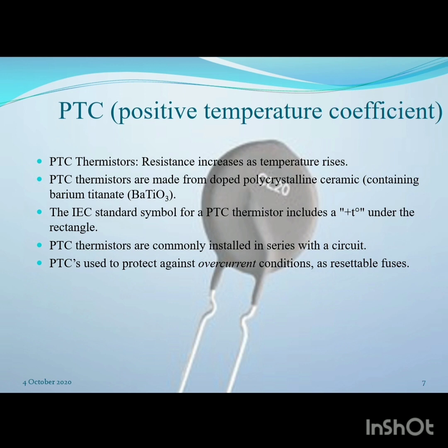Barium titanate is a ferroelectric, and its dielectric constant varies with temperature. The high dielectric constant prevents the formation of potential barriers between the crystal grains, leading to a low resistance. So in this region the device has a small negative temperature coefficient. At the Curie point temperature, the dielectric constant drops sufficiently to allow the formation of potential barriers at the grain boundaries, and the resistance increases sharply with temperature. At even higher temperatures the material reverts to NTC behavior.